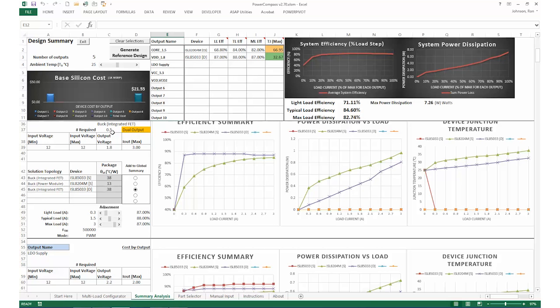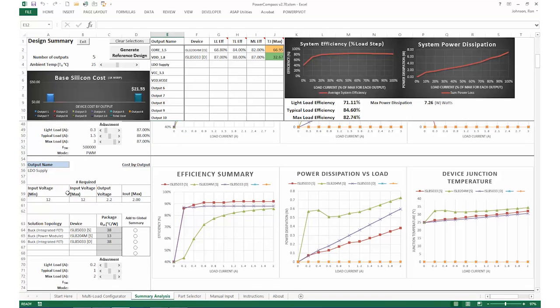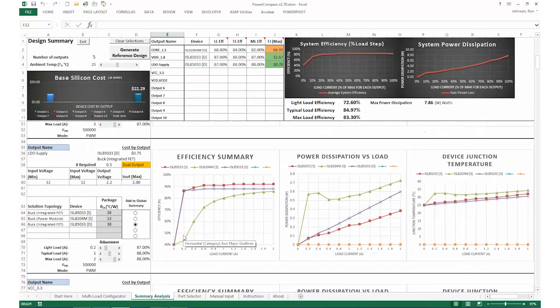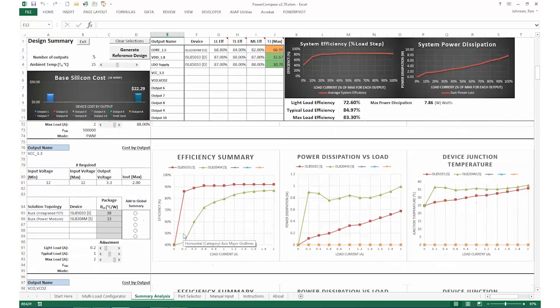And you'll notice when I select it, it comes up here as a dual output. It's only half of the solution. So I'd come down to the next rail, where the 85033 was also suggested as the secondary rail, and I would select it as well. When you're dealing with dual output devices, you need to select it for both rails, otherwise the system will give you an error when you try to generate the schematic and make you correct it. We'll go down to the next rail, and you can see the difference.